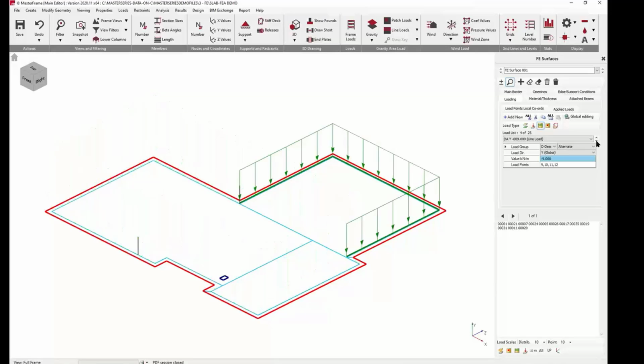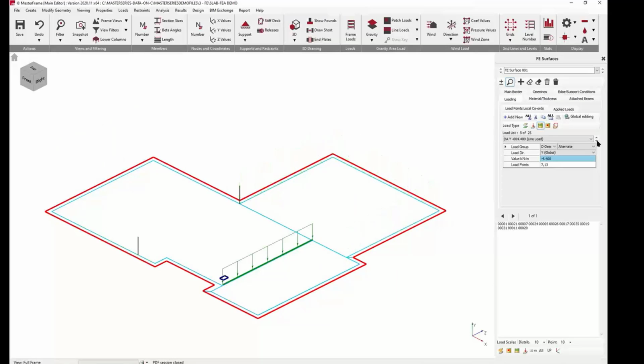Line loads from walls on the 2-story and line loads from walls on the 1-story. Internal wall, and then edge walls, that's dead and live spanning across there, dead and live spanning across there, and dead and live spanning across there. The dead and live here is coming down onto these 2 point loads.